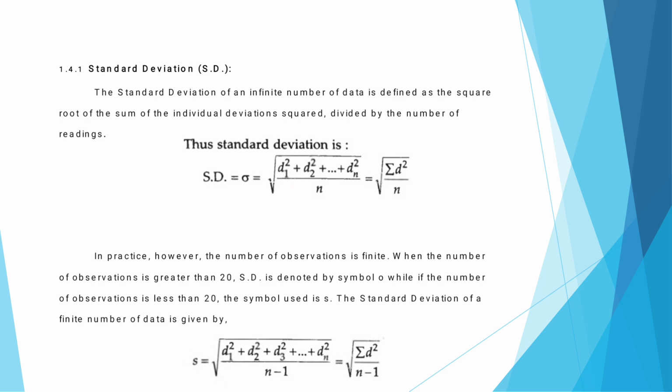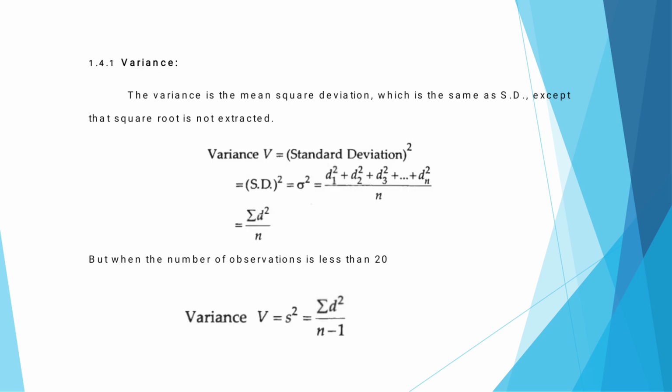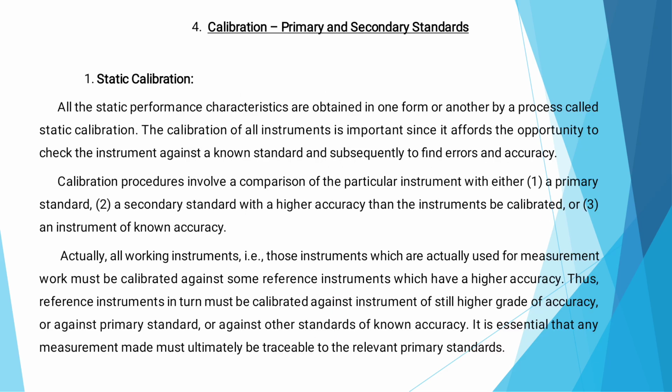And to illustrate how these measurements work in practice: first, pressure is converted into physical displacement, making the Bourdon tube the primary transducer. Next, the displacement is converted to electrical voltage, making the LVDT the secondary transducer. So this will demonstrate how multiple stages of the measurement interact. So these are the applications.